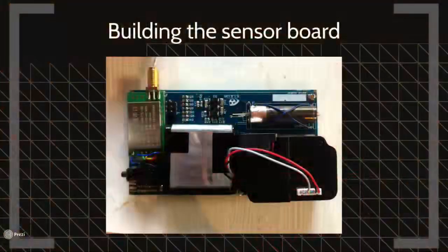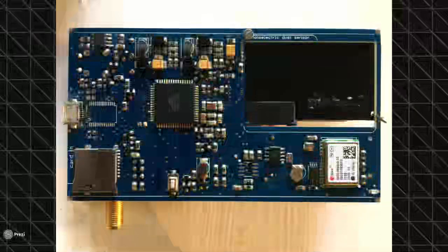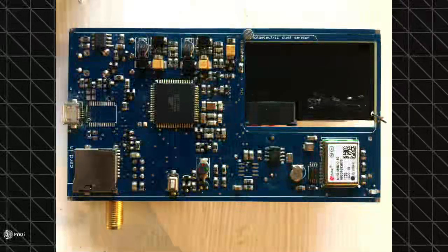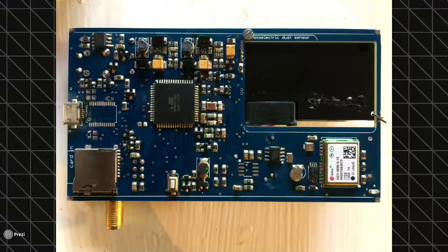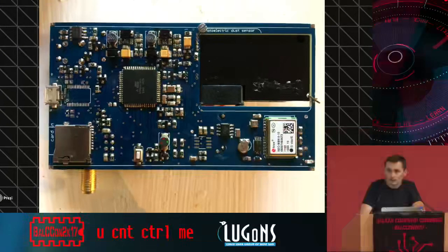And I needed a way to get the data. So this board, let me switch it over, already had a micro SD slot, and that is really useful to make a data logger. Instead, you can just go for a cheap data logger which has the microcontroller and has the SD card on board. There are plenty available. You just add the sensors. But I had this board and I wanted to go for it.